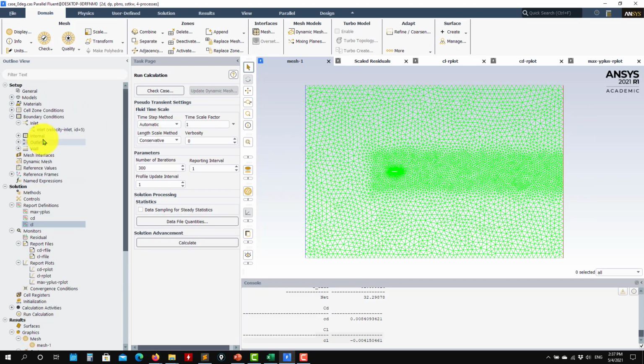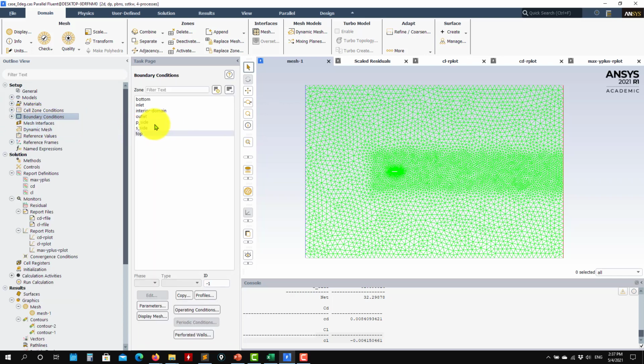But the difference here, look at your boundary conditions, okay? So you have inlet and outlet, but if we want to change the angle now, you also need to change the boundary conditions. So now this is an inlet, but also this is an inlet. So we need to start to change the boundary conditions, and this will become outlet, outlet, inlet, and inlet. So you have to be careful, extra careful here.